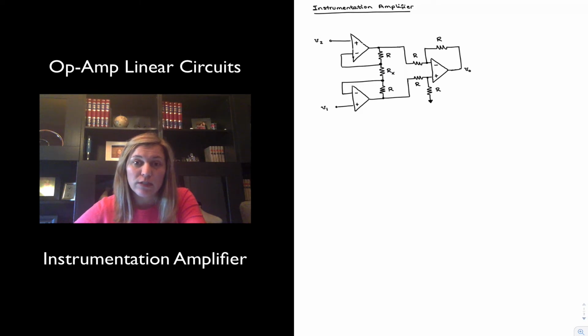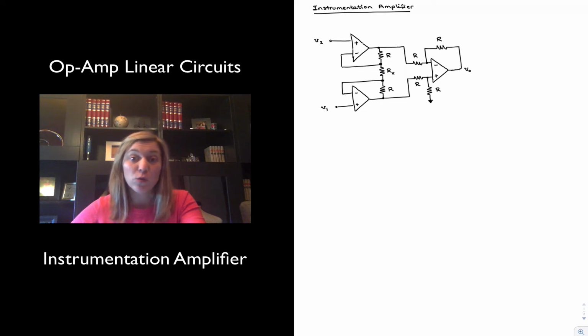differential voltage signal in cases where the value of the differential voltage signal is very small, maybe in the range of microvolts, as well as when you're dealing with noisy environments, and it is noise that is likely to be picked up on both inputs of your amplifier system, and so it can be considered common mode noise. It's present on both inputs.